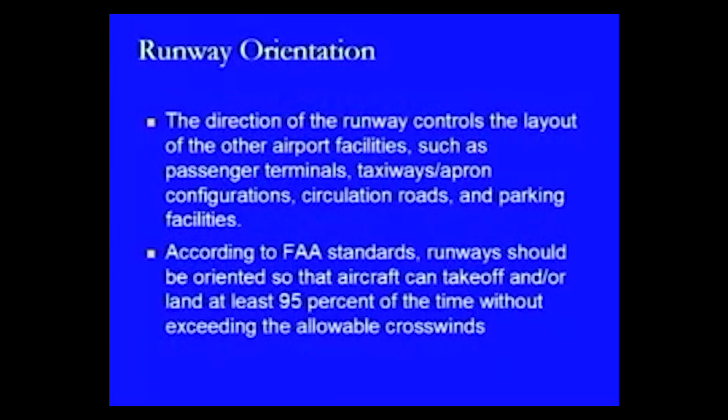According to FAA standards, runways should be oriented so that aircraft can take off and land at least 95% of the time without exceeding the allowable crosswinds.